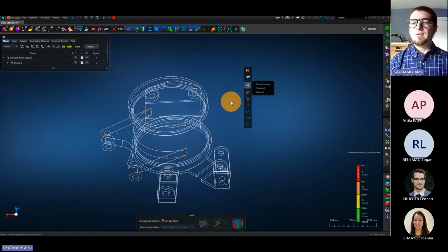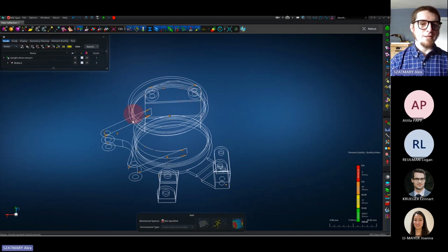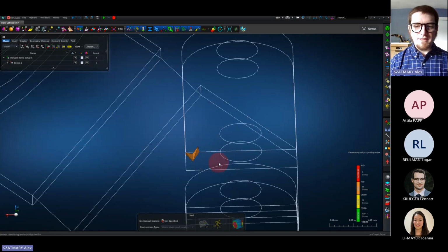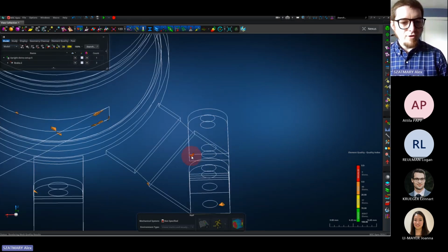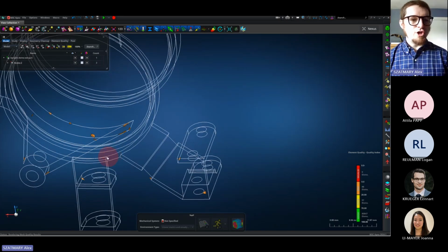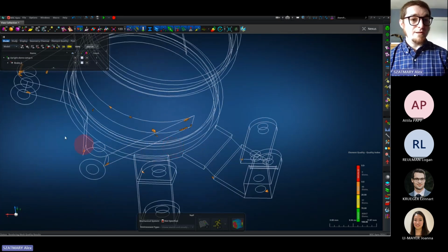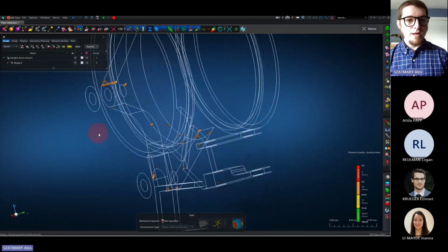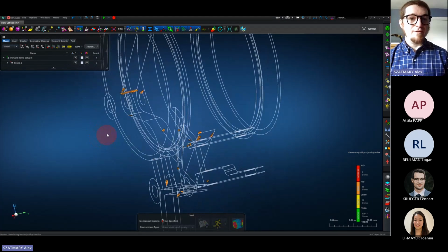And what I'm doing right now is just changing what things my mouse is selecting so the part doesn't highlight in a clumsy way. Okay. We also see, like, I should probably have a fillet down there, and I don't, and so it's hard for the mesh to be very smooth right there. I should definitely have a fillet at that seam there. And I would want to go change those in my CAD model, ideally, although you actually can edit your geometry in Apex really easily to add in fillets.